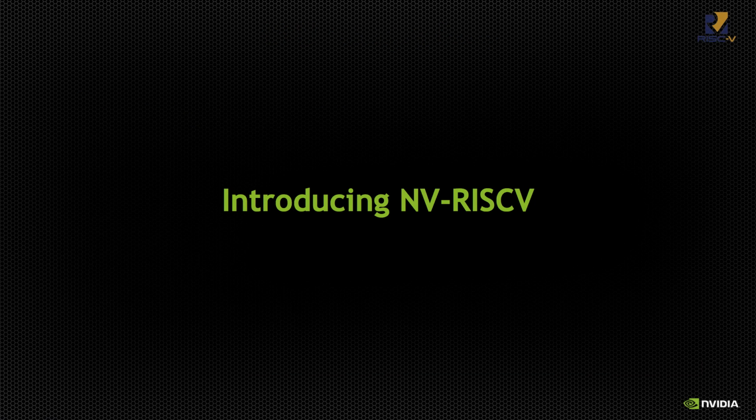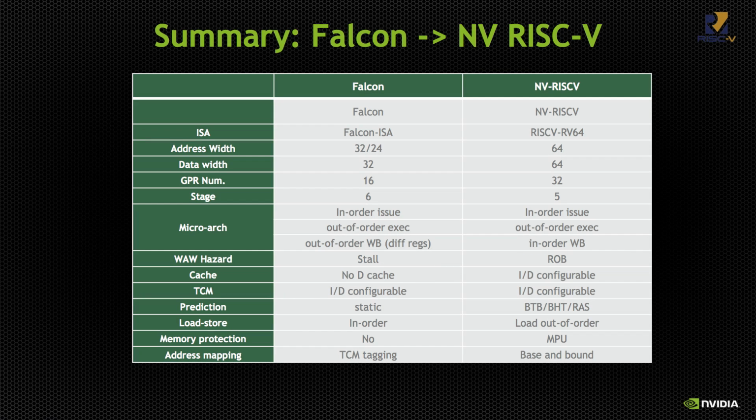Next, I'm going to introduce the NVIDIA RISC-V architecture. This is a summary comparison of our old architecture and the new architecture, which is RISC-V based. So basically, the first generation of NV-RISCV will be very similar to the Rocket Core. It is an in-order issue machine. It has out-of-order execution, in-order write back.